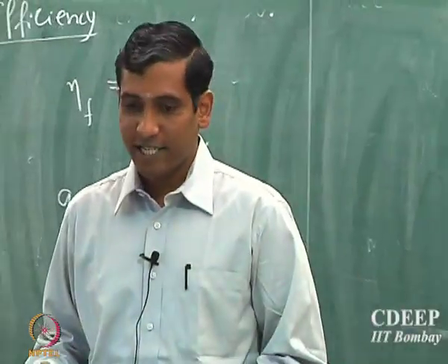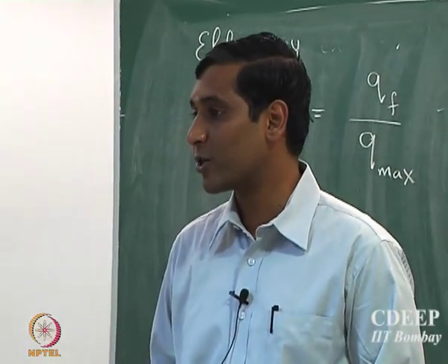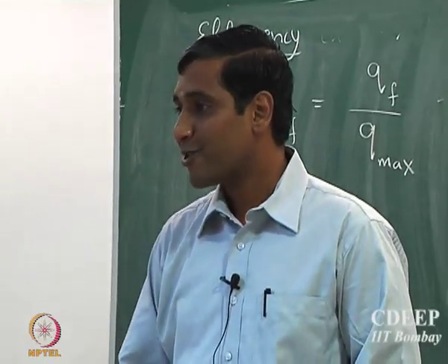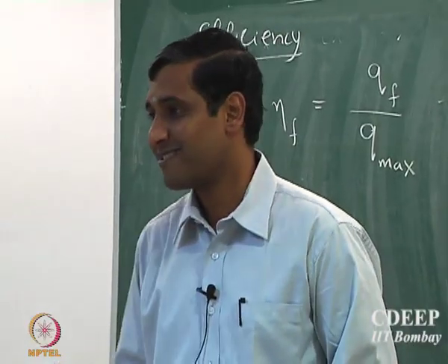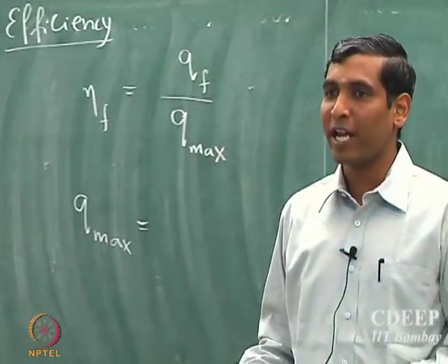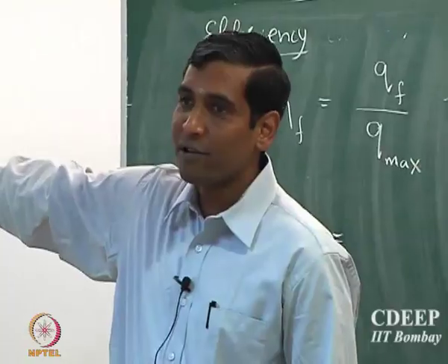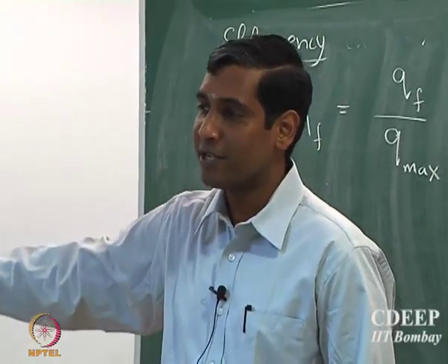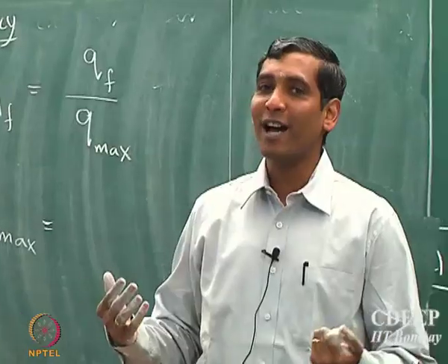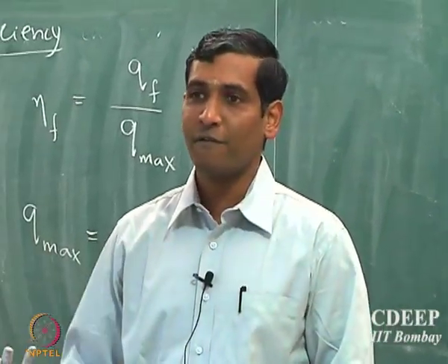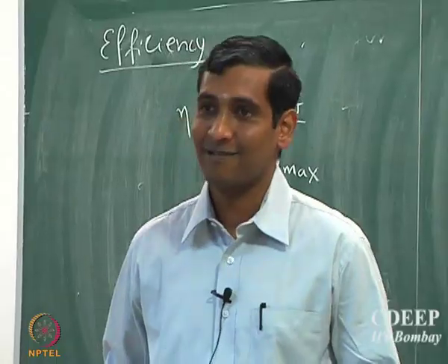In fact, if the temperature at the right end is T infinity, then the temperature gradient, or driving force, for convection is almost 0 at the end of the fin. Which means that the end of the fin is almost of no use. Any heat transport rate is governed by the temperature gradient, which is the driving force. So if the temperature at the end of the fin is equal to that of the fluid temperature, it's no use. You don't want to design a system where some parts of your fin have a 0 driving force. That's useless. It's a waste of money.